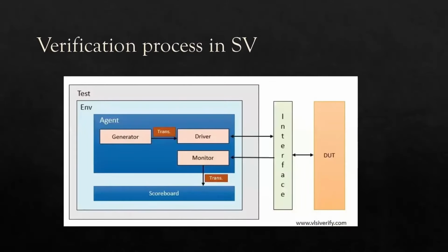See, when it comes to Verilog, we don't have any particular architecture. In the Verilog test bench, it's very simple. If you have inputs, just assign A equals 10, B equals 20, and expect the output. That's very simple. If you have a simple design, then it's fine. Verilog can help, but when it comes to complex designs, the SystemVerilog test bench will help a lot. So through this SystemVerilog test bench, you will verify.